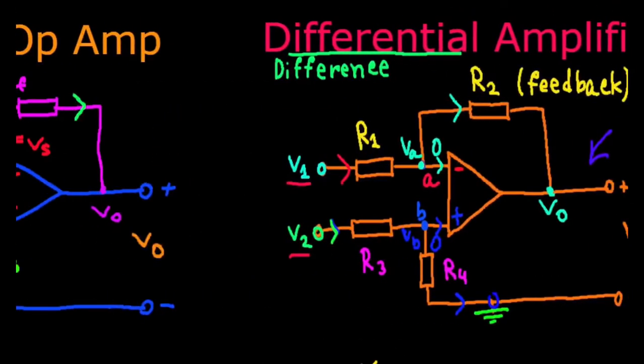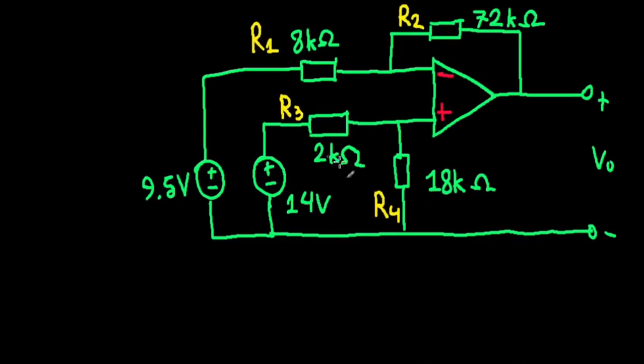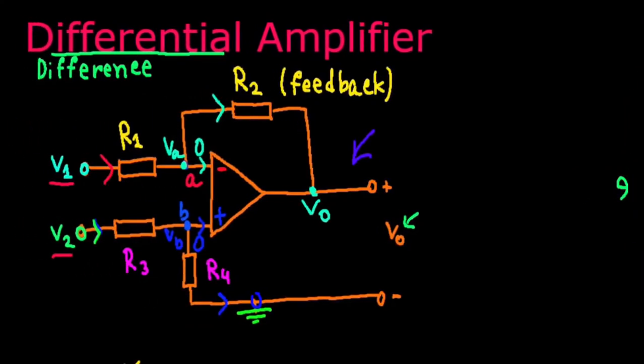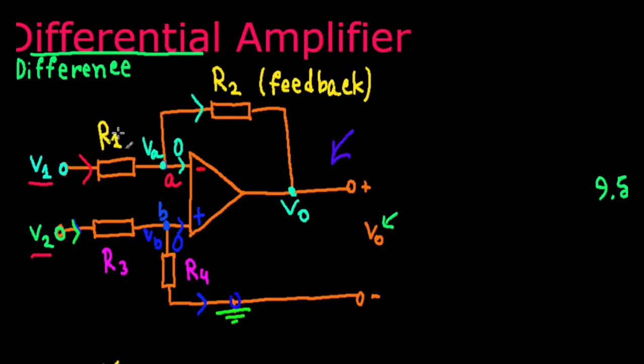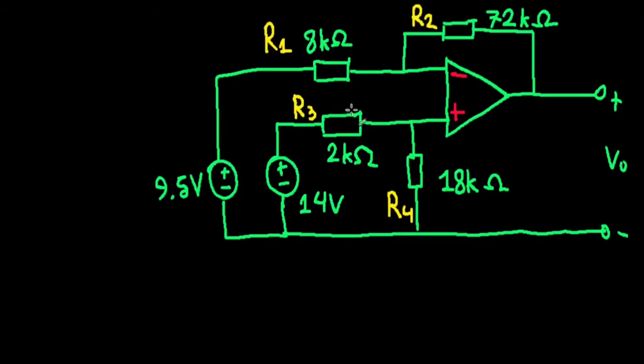We did one before, but we'll do more of them when we deal with multiple op amps. Anyways, that's for later. I just pattern match the resistances with what we have here. So on the non-inverting input side, from left to right, from V1 up to here, this is R1 and R2. Similarly, this is R3 and this is R4, and this should be my ground, my virtual ground.